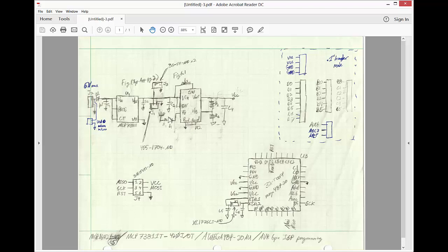But one of the trade-offs for that is to program it. I don't get any fancy programming. I can't just plug it into USB and download. Instead, I went with a tried and true original, a 6-pin AVR ISP programmer. And you can see that 6-pin programmer right here. From there, I broke out as many pins as I could. I'm planning to put them all in 0.1 inch header on a 0.1 inch grid. So this, in theory, would allow me to plug it into a white breadboard or something of that nature to allow me to actually interface parts to it as I went and did this.